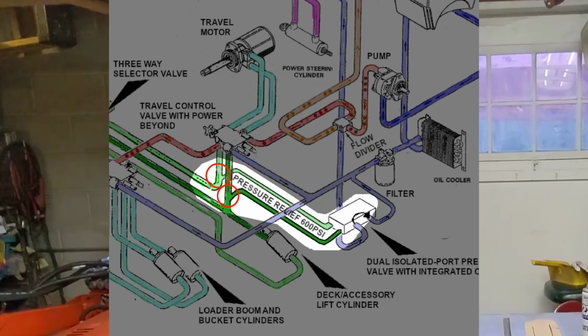So I mulled it over for a couple days, imagining how I could replace or reinforce the deck lift cylinder, what it would take to replace all the lift lines and the diverter valve with heavier duty versions. But wait, what if I could introduce a pressure relief tee into the lift lines themselves after the oil has left the valve body? Then I could crank up the lift circuit's pressure relief, but that higher pressure would vent harmlessly before it ever reached the various lift circuit components.